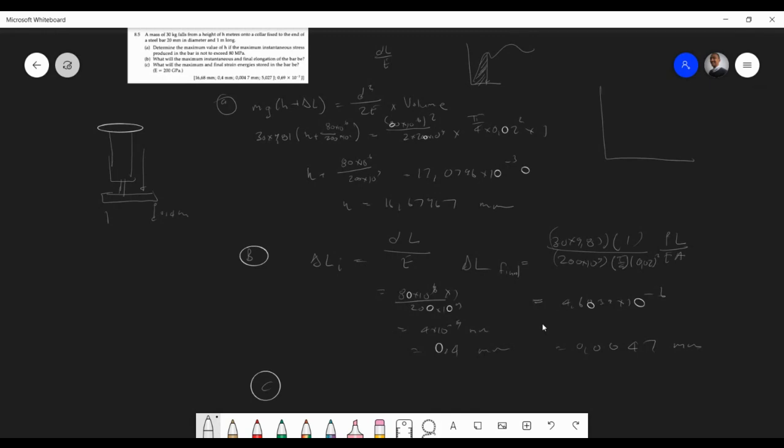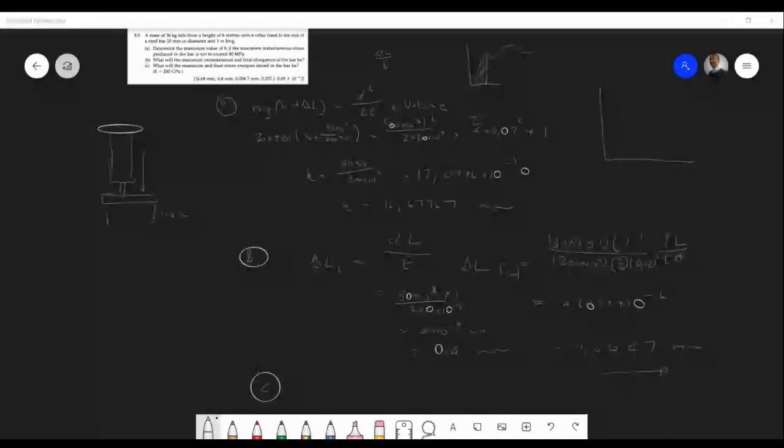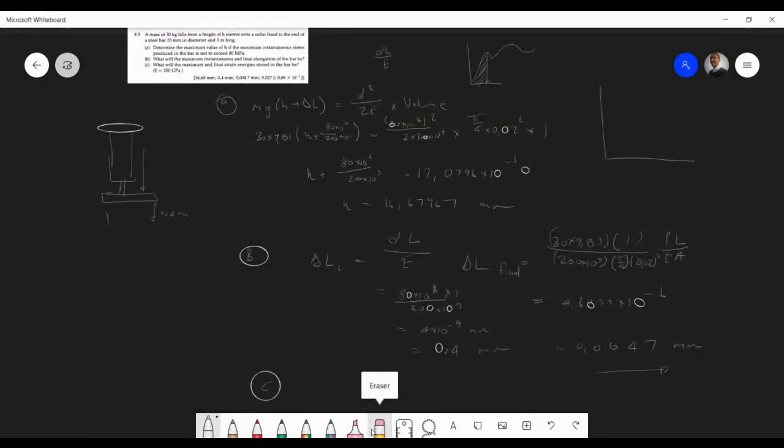It goes down 0.4. However, when it settles eventually, it settles obviously to this load over here, this 30 times 9.8, and we get 0.0047. The final is just a weight resting on the collar. So it falls down, gets deformed by 0.4, and then eventually reverts back, and all that's left is in essence the weight on the column. That's all it really means.